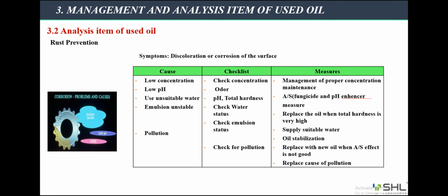About causes: low concentration, low pH, use of unsuitable water, unstable emulsion, pollution. To check this situation, we need to check concentration, odor, pH, total hardness, check water status, check emulsion status, and check for pollution.